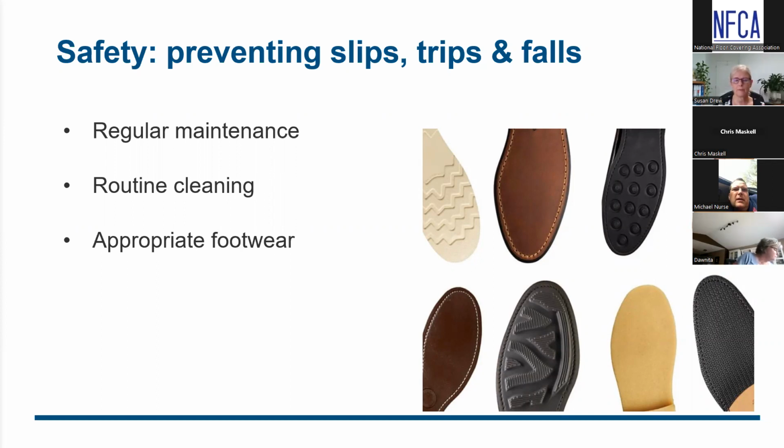So a sudden elevation of 1/8 that you would get with the transition. Yeah, maximum. Preferably none. Preferably no transitions would be great. Well, we have those construction joints where slabs stop and start, and those gaps must be carried all the way through the system. So inevitably you have a transition there.